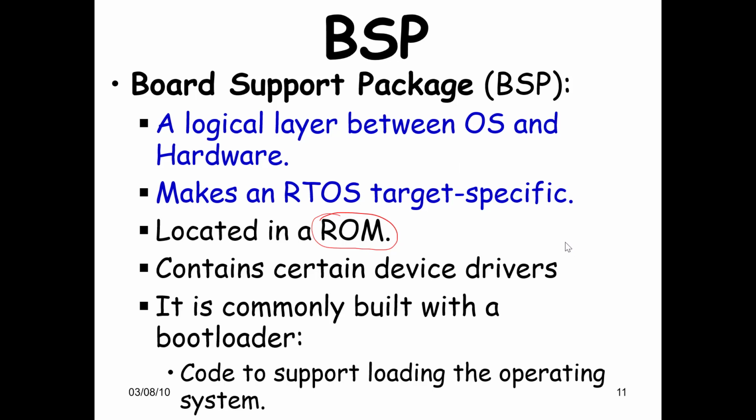So regardless of the device, if a standard interface is presented, then the real-time kernel will find it much easier to talk to this hardware. Also, particularly with regards to determinism, timing, and jitter, it is possible to have constraints as well as guarantees embedded in such layers, such that higher-level software can have an idea of what are the worst-case numbers it is looking at.